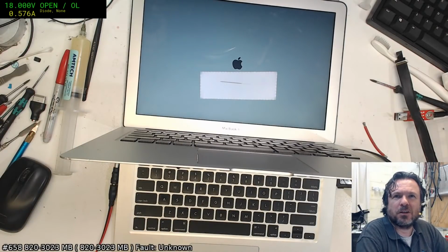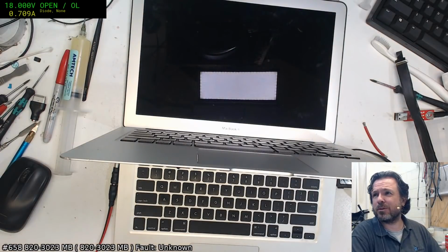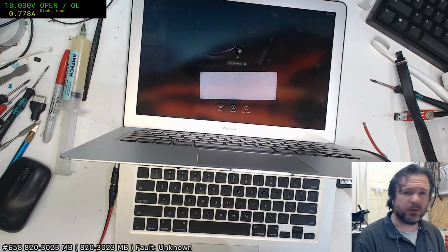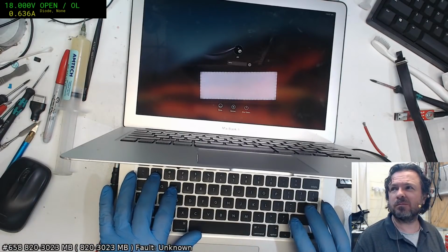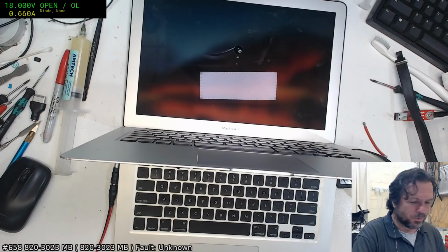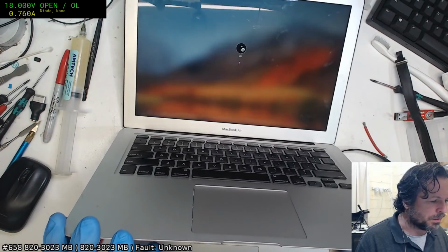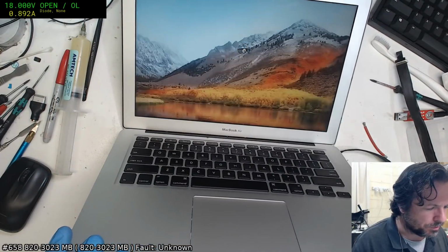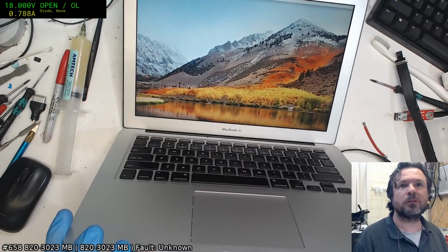Okay, so you've got a 1398, 2013. Oh, they'll probably be your VRMs. Yeah, they'll probably be your voltage regulator modules, which are a whole bunch of fun to replace. I mean, it's entirely doable, but it's certainly not something you want to do if you haven't done it before without a test machine to play with.